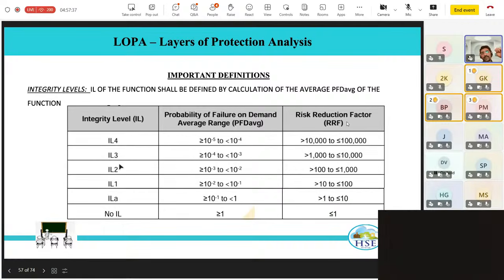That is why in our oil and gas systems, they insist on relooking at the design and not going for such high level integrated SIL 4 systems. I would suspect you would not have encountered any of those unless you are in a nuclear setup. Okay, so this is the definition of SIL or integrity levels.